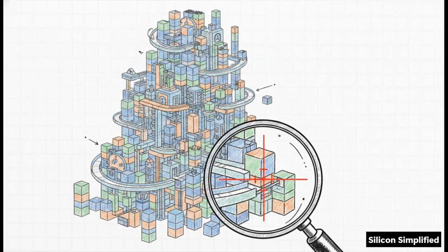So the ultimate goal here is that by combining these modular sequences, you can aggressively hunt down obscure corner cases without rewriting your core test bench. Because sequences are simply class objects, they can instantiate and execute other sequences. You build up a library of small, highly focused unit tests, and then you compose them hierarchically to create massive, intricate test scenarios that just push your design to its absolute breaking point.